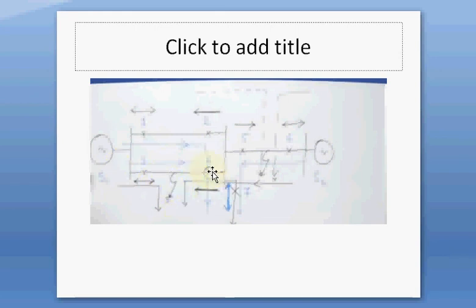Now whenever a fault occurs between relay 3 and relay 4, the current will flow in this direction from this source, so relay 5 will not operate, but relay 6 will operate, just because the current now exceeds the pickup value of the current. Therefore the relay at position 6 will operate, the relay at position 5 will not operate.